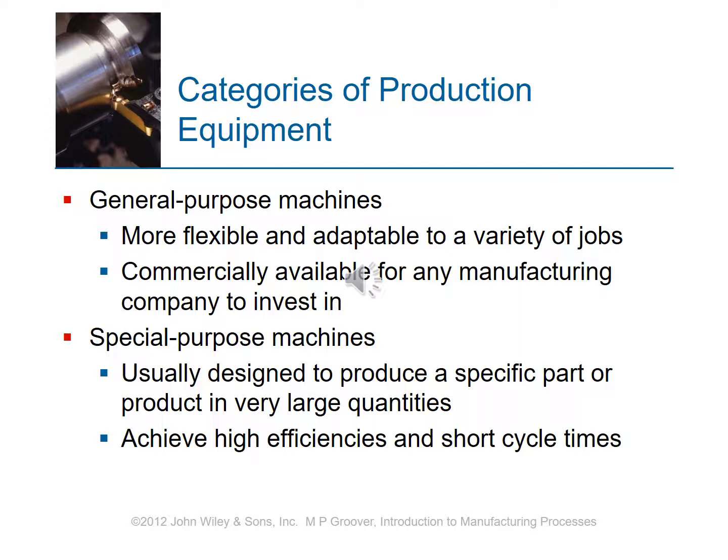You've got different types of equipment. You've got general purpose machines. These are a skill saw, a drill, things like that. Things you can basically go to Lowe's and buy and use, right? Then you've got the special purpose machines. These things are custom made. We used to have special made grinders for our hydraulics because we were trying to hold such a tight tolerance. But generally what you're looking for is high productivity and short cycle times. Just get these things made and out of there.